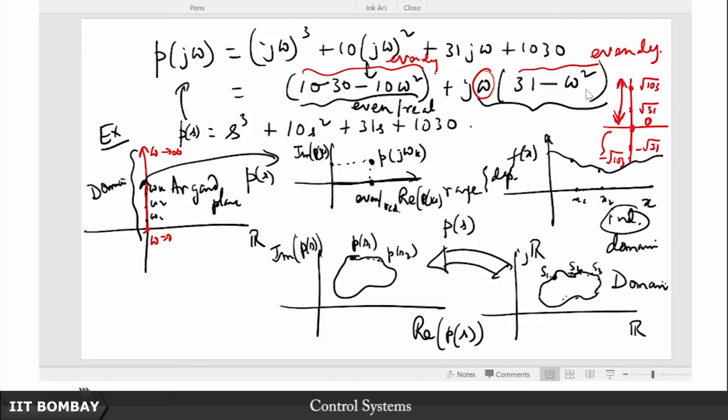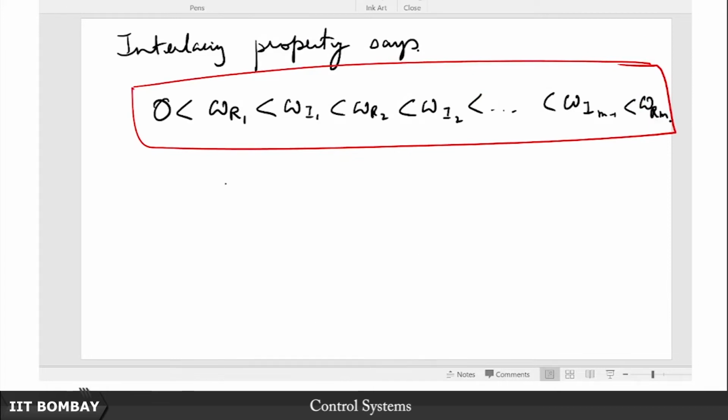that's why based on what I study of this third degree polynomial, I will say that if the third degree polynomial follows this interlacing property, the original 20th degree polynomial will also follow this interlacing property. That is the idea. So how can I do this? It turns out that this is where this Routh criteria, this special smart way of doing this, helps us.